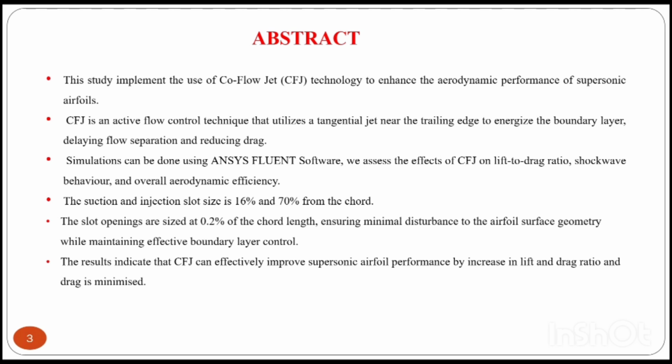Here, CFJ is used as a secondary flow control method to improve aerodynamic performance and stall characteristics. For simulation, we used ANSYS Fluent software for the analysis to find the aerodynamic performance and stall characteristics. Due to the high pressure on the lower surface of the airfoil, we have installed the suction port near the leading edge and the injection port near the trailing edge. The results indicate that CFJ can effectively improve supersonic airfoil performance by increasing the lift to drag ratio, and drag